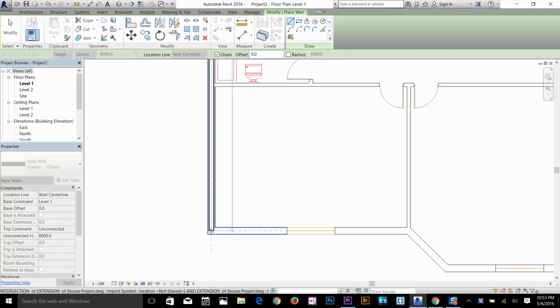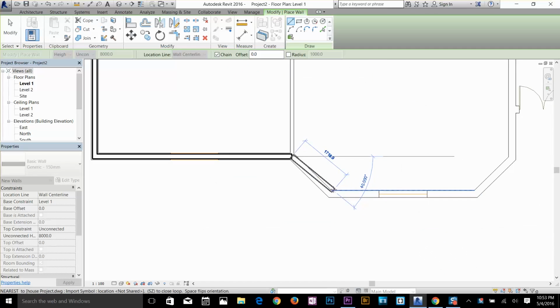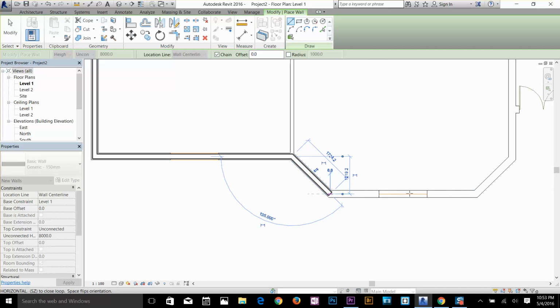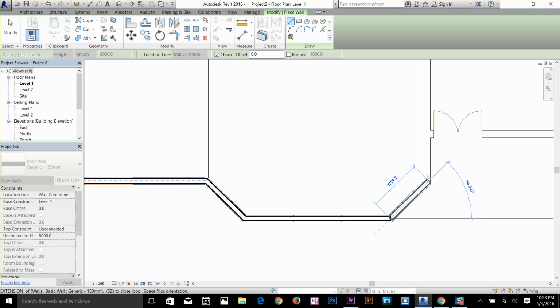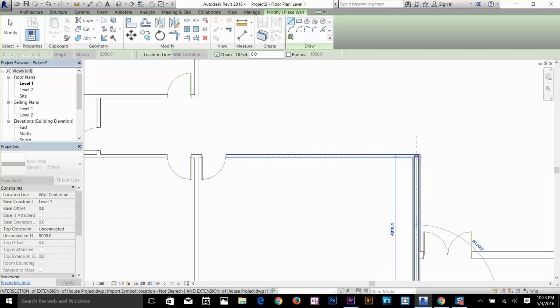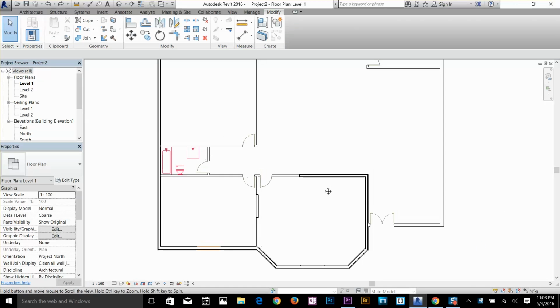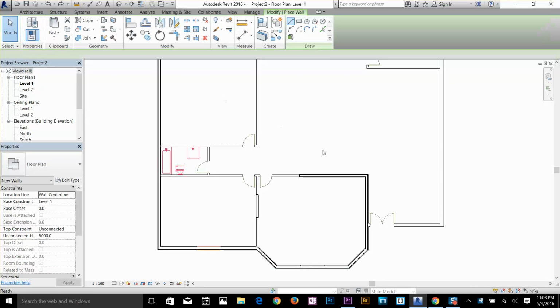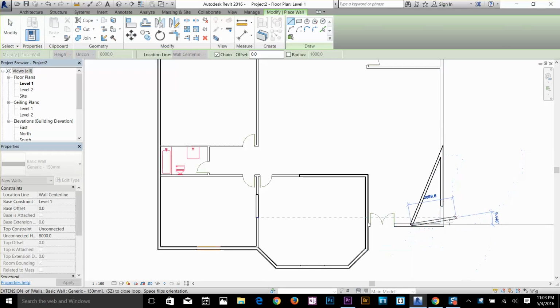And let's say you draw a wall here and then draw a wall here, and as you can see Revit is already fixing that up for you, so it will snap to that midpoint and you can just keep going like this. I'm gonna show you a better way to do that. It's quite quicker. So what I want to do is select my wall command again, and I want to select this, just a rough wall.